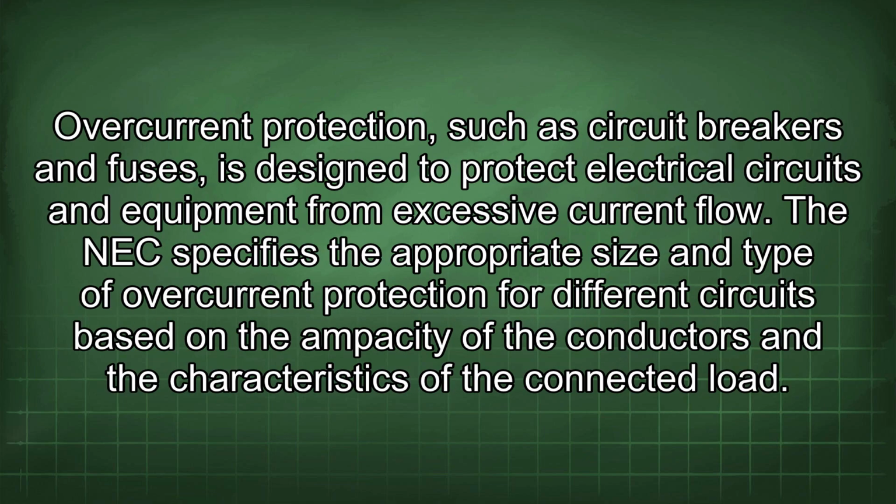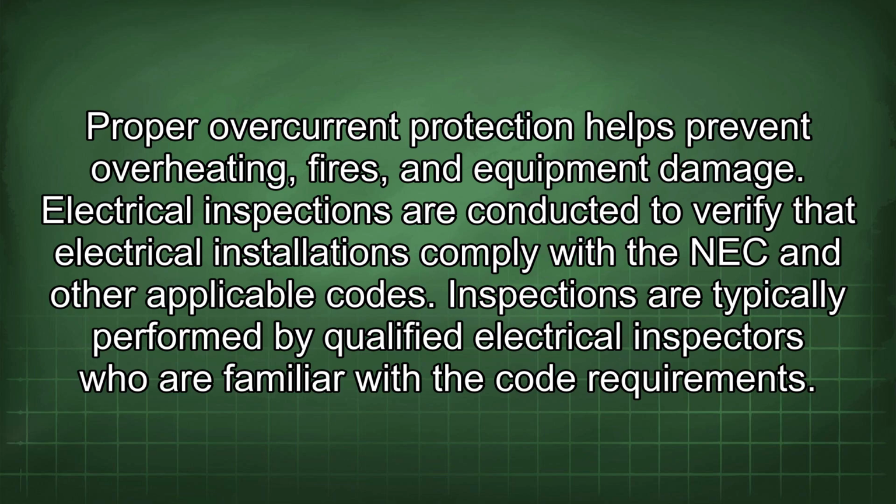Overcurrent protection, such as circuit breakers and fuses, is designed to protect electrical circuits and equipment from excessive current flow. The NEC specifies the appropriate size and type of overcurrent protection for different circuits based on the ampacity of the conductors and the characteristics of the connected load. Proper overcurrent protection helps prevent overheating, fires, and equipment damage.